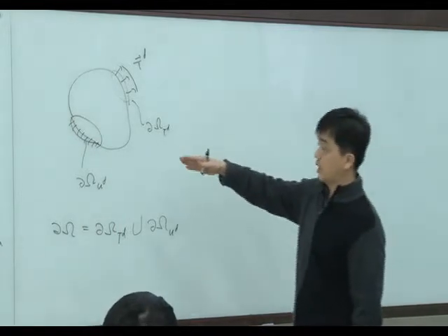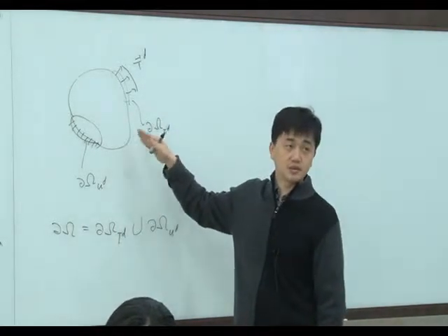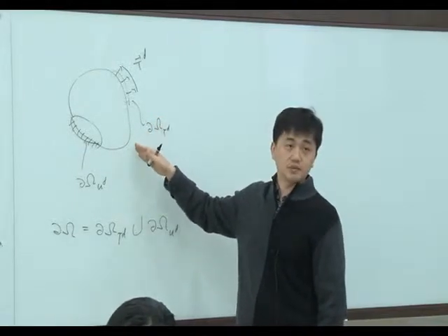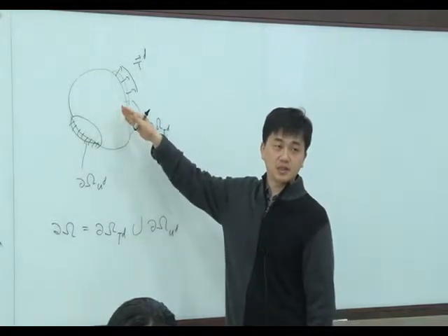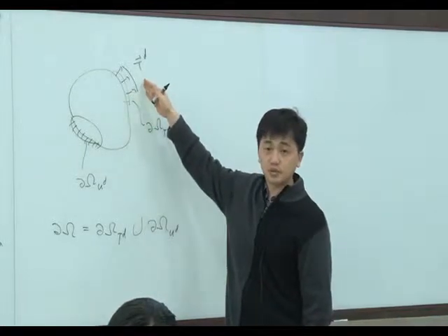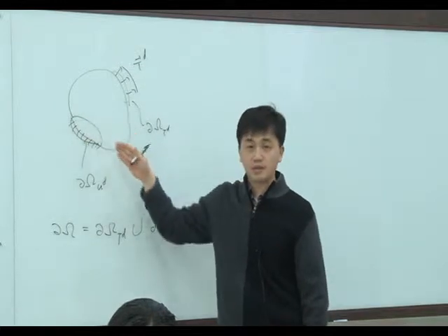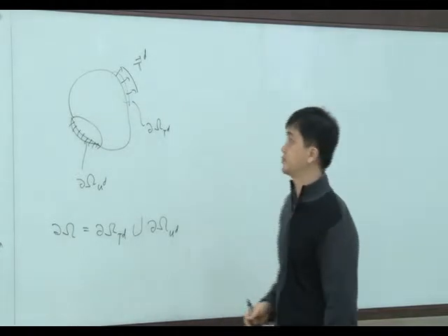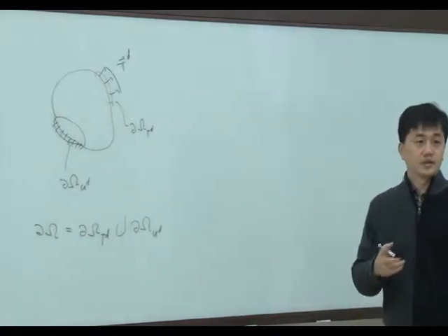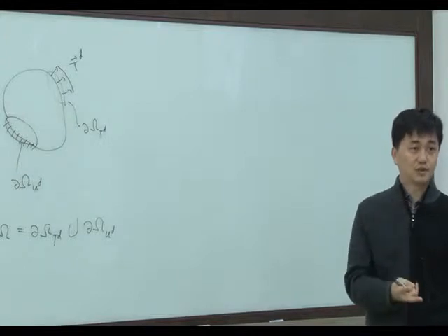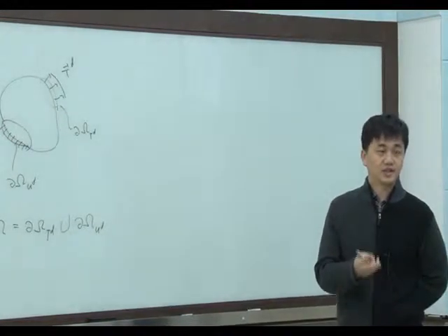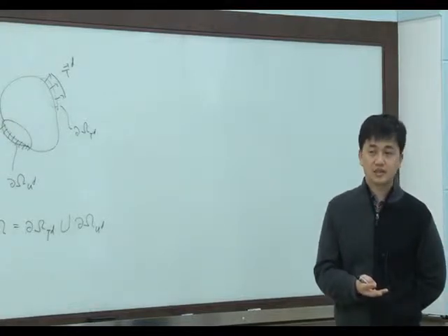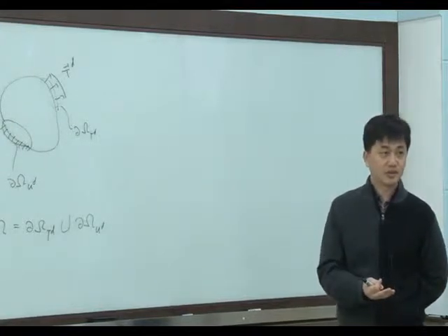This is a very typical structural problem, also a solid mechanics problem. We have a body, it is subjected to some force, and it has some displacement boundary condition. In general, we have two boundary conditions in static analysis: force boundary and displacement boundary, right?